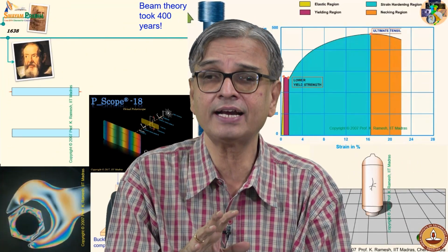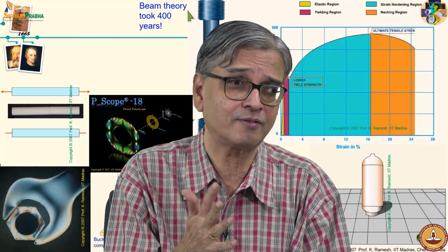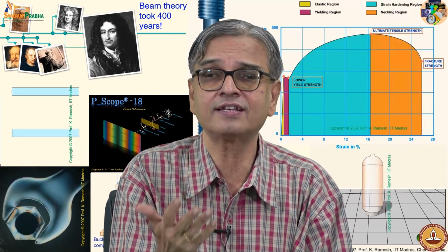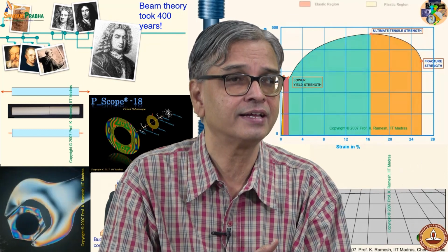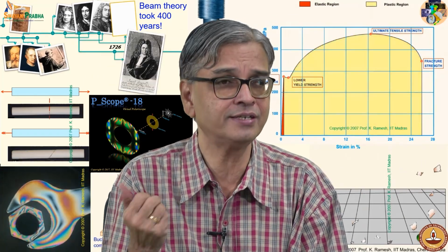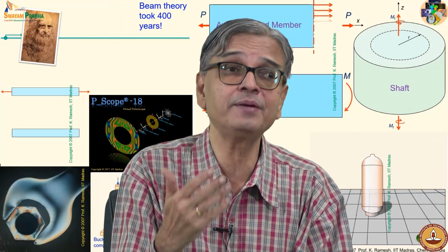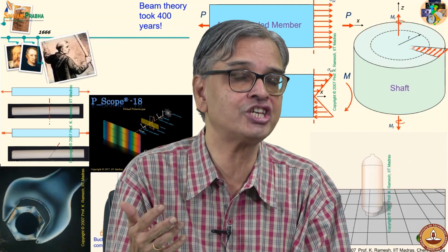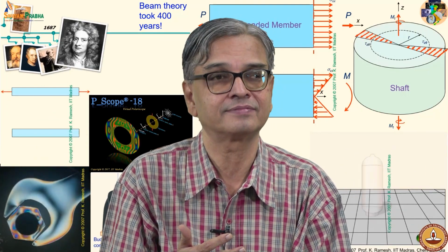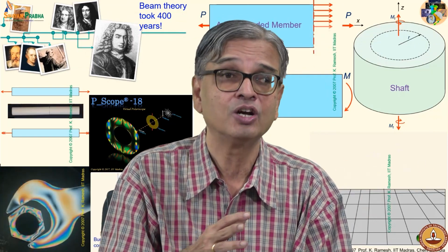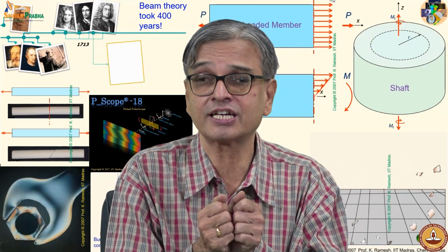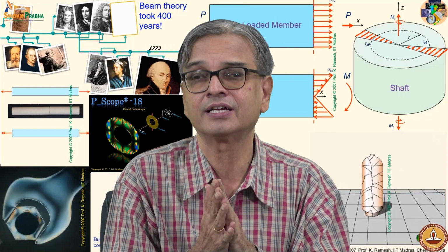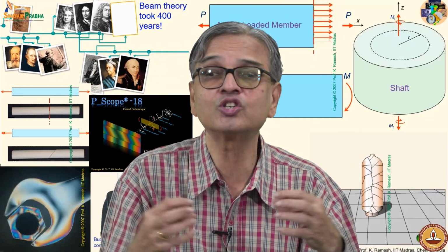And we have also looked at a priori what the result is, how resistance develops in simple tension, how the resistance develops in bending, how the resistance develops in torsion, but we could see experimentally by photoelasticity the play of colors in tension and bending. That has given an inference, what I said, that the cross section equally participates in axial tension, whereas in the case of bending, the inner core does not contribute to load sharing.